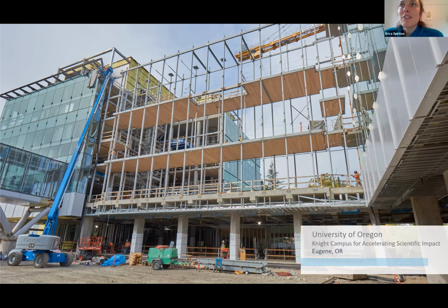So I think some of the considerations here are just around minimum bearing, making sure that the CLT panel has enough steel to bear on, and making sure that that is designed with consideration for steel beam sway and the tolerances that steel is both manufactured to and how it behaves in hot weather and things like that. Interestingly, steel and wood both move, but they move in different conditions. Steel moves when it's hot and wood moves when it's wet. So just want to think about the interface between those two materials and design details that are forgiving of those kinds of situations.